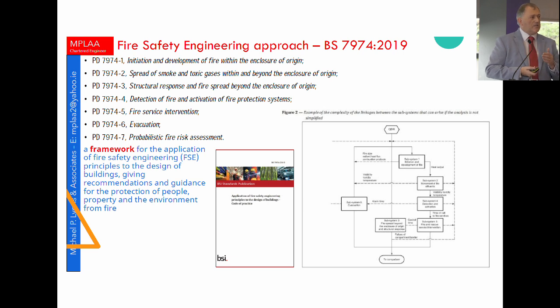And then also a section on fire service intervention. And that can be an important one that people get wrong. People really have to understand how the fire brigade arrive at the building, how they set themselves up, the facilities, the resources, the measures that the fire brigade will use, how they will actually get to the different seats of fire, how they'll use the building itself, particularly with performance-based buildings, how they're evacuating and how the fire brigade get in while they evacuate.